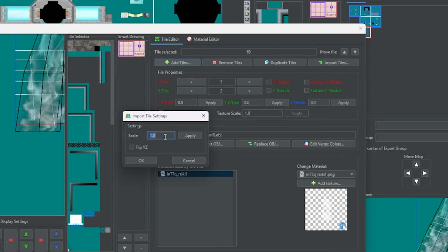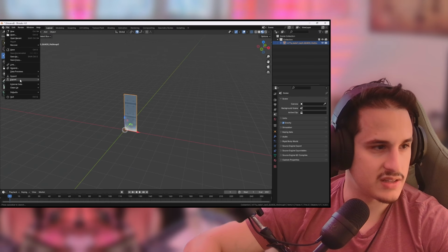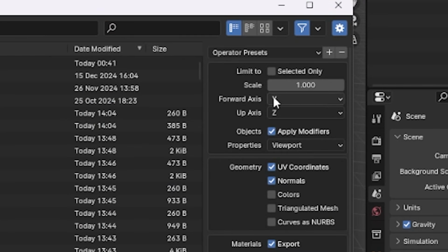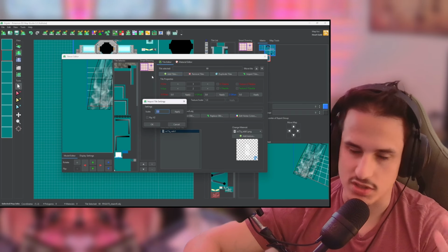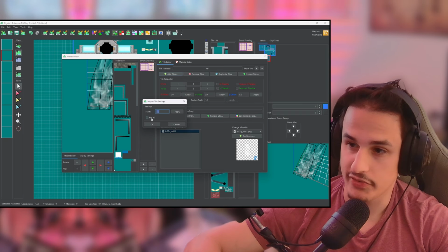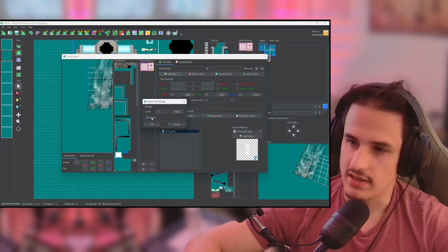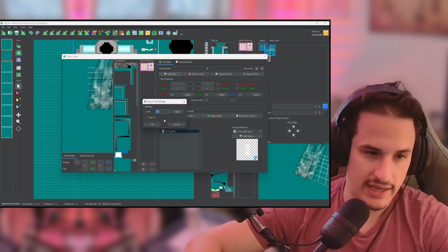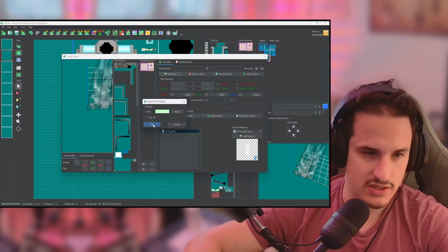And because we've already oriented everything correctly, oh, I should mention that when you do export stuff, this is not a default. So I'm going to go back here real quick. You want to make sure your forward axis is Y and your up axis is Z here. I already have that set, but by default that's not the case, so just make sure. If it's not flipped, then you can just click flip XY or flip YZ here. That'll fix the problem if it gets imported in the wrong direction. I keep scale as 1 because we already scaled things down. So I'm going to hit OK.